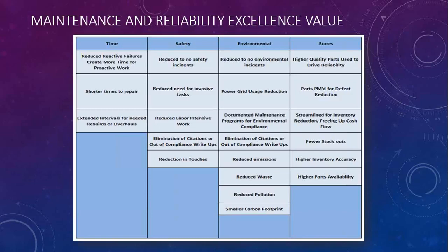It reduces the need for invasive tasks. You're touching the machines less, reducing the intensive labor work because you're finding the defects early on in their failure, where you're only replacing a bearing versus replacing an entire assembly. So you reduce the risk of safety incidents that way.